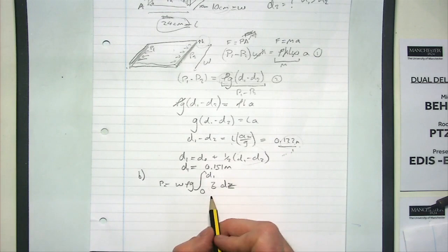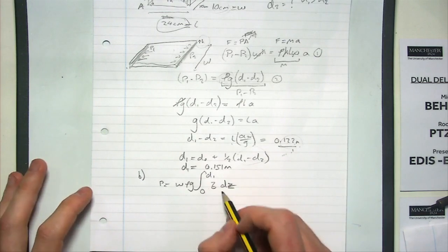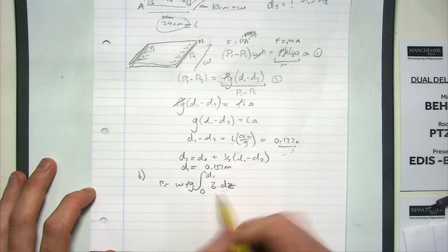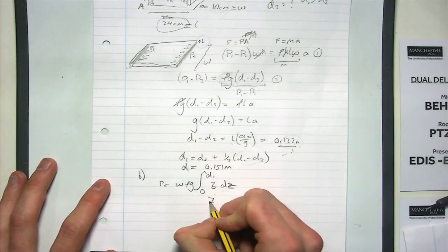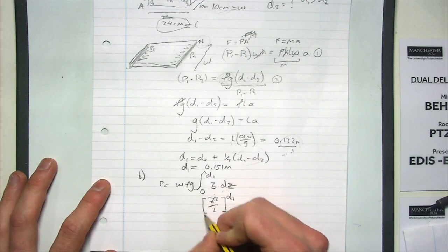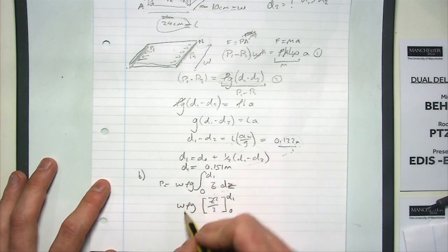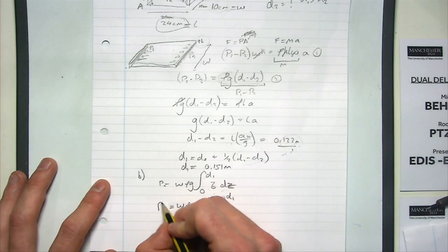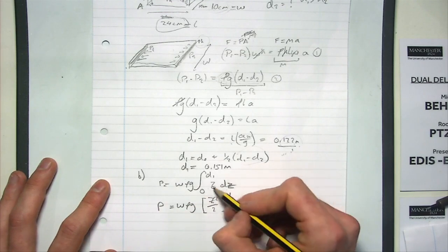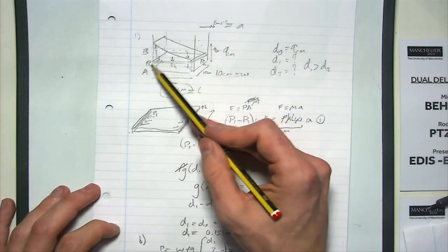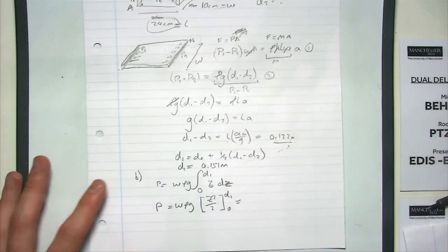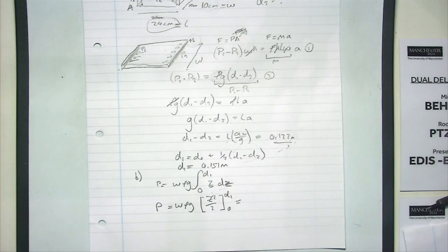So when we do this integral, can anyone tell me what this integrates to? Anyone? Z squared divided by 2. Yes, z squared divided by 2, right? It's between d1 and 0, and then we've got this factor out here that makes it into a pressure through the units, right? So that's just an integral. All I'm saying here is take tiny little chunks of this and add them up to create the area, okay? Because if you remember, the way integrals work is you take a tiny little slice,